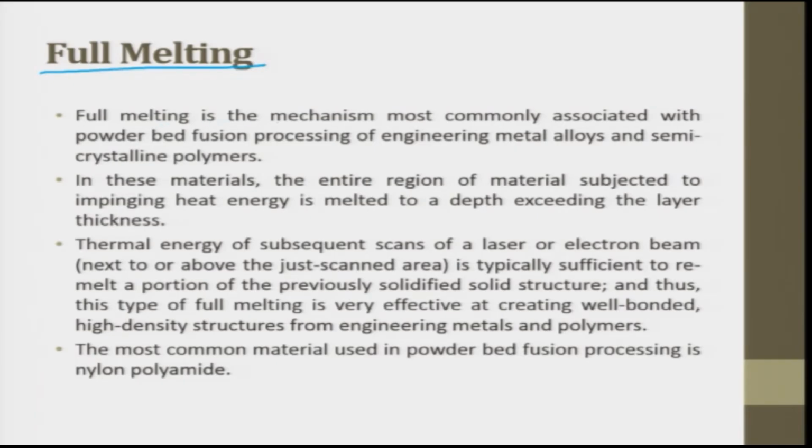Full melting is the mechanism most commonly associated with the powder bed fusion processing of engineering metal alloys and semi-crystalline polymers. In these materials, the entire region of material subjected to impinging heat energy is melted to a depth exceeding the layer thickness.